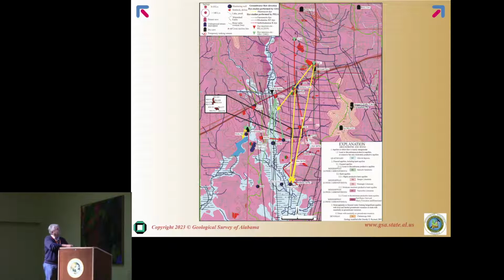Here is a karst hydrogeologic map, which I made. For the limestone I used a range of pink colors, and most of the site, this medium pink color, is Tuscumbia limestone, and along Indian Creek at low elevation, it's Fort Payne chert, and on the ridges, you can find Monteagle and Bangor limestone.